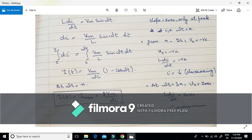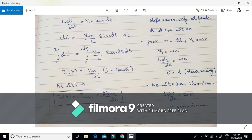During the positive cycle, this inductor gets charged. Since this I of t current is obtained from 0 to pi, because of that driving force, that is the source voltage, the inductor is charging, and the diode is conducting.